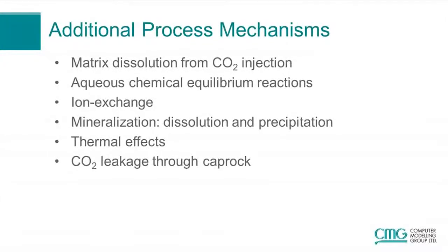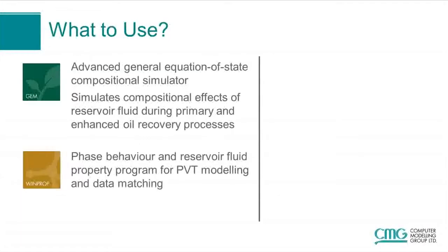Back to you, Hussein. So as I mentioned, we need to have a modeling tool to capture all of these mechanisms. In the CMG package, we have GEM, an advanced general equation of state compositional simulator. This simulator can be used to simulate the compositional variation in the reservoir fluid during the primary and enhanced oil recovery processes. Also, we have the WinProp package that can be used to generate a PVT model based on matching the lab experimental data.